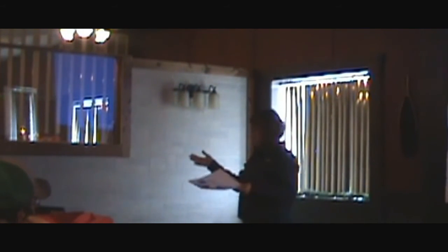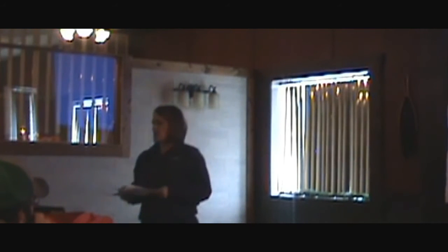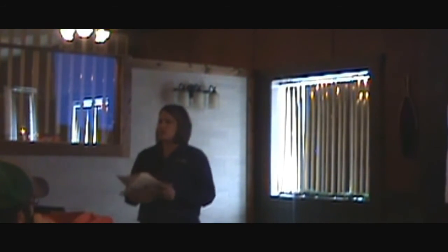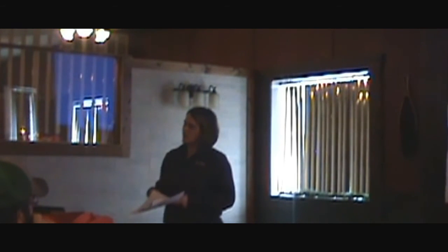That's a 3-year contract, and the irrigation water management plan is just that we help you decide how to use that prescription correctly. And then we want you to install soil moisture meters with that so that you can use the information on what the percentage of water is in the soil to determine when to water essentially.